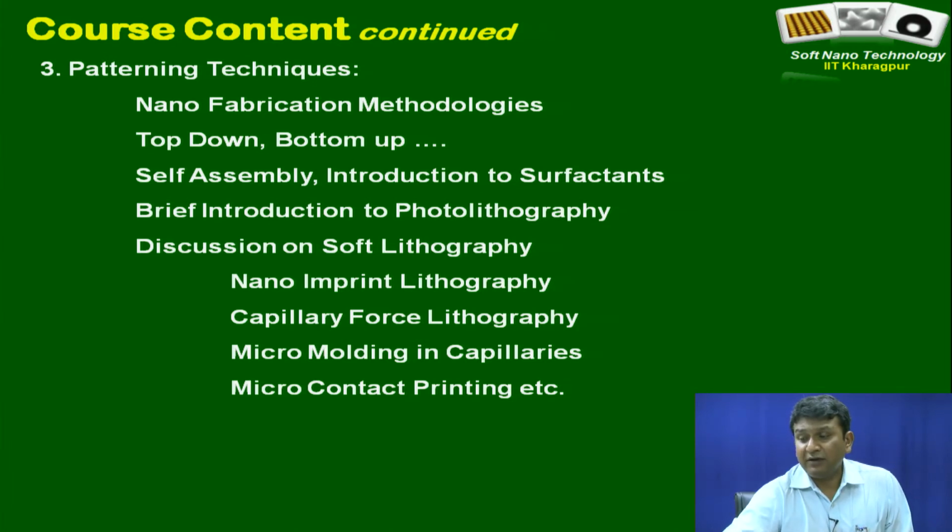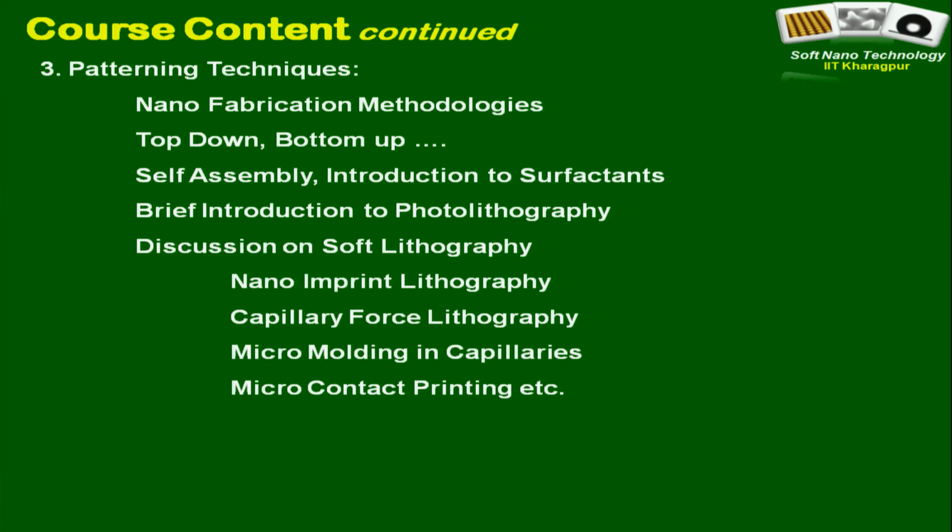Right. So just now I received a question from Mr. Sri Pratap, how laser is involved in nanotechnology. Actually that is a part of the thing we did not talk about. Laser and other beams like electron beam, ion beam, they are critical to direct writing methods like focused ion beam lithography, laser interference lithography, electron beam lithography and stuff like that, where what you do is you essentially raster.